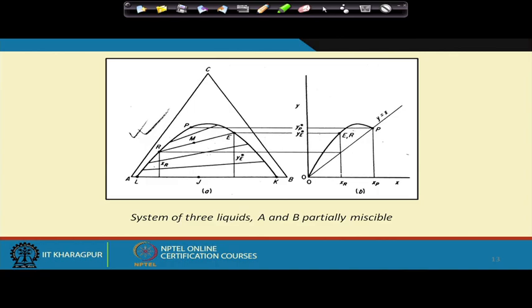Well, the last thing which I would like to discuss with you is liquid-liquid extraction. In this case, as I have already mentioned, when we are dealing with liquid-vapor cases, the gas phase is always miscible, while the liquid phase may or may not be miscible. So, usually a two-dimensional plot of the two equilibrium concentrations under different conditions of temperature and pressure is sufficient to generate an equilibrium plot. But in liquid-liquid equilibrium, as I have mentioned a short while ago, we find that there are mutual solubilities among the different components. Let us take a concrete example.